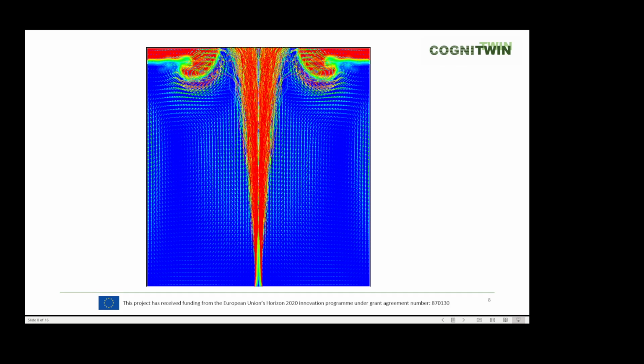On the top there is red slag, which is being pushed to the side by the upcoming steel flow. And the arrows that we see indicate the flows in the steel. So we simulated a number of scenarios here with different gas flow rates and also different vacuum pressures above the melt. The vacuum pressure above the melt is important because in the case of low pressure, the gas bubbles expand dramatically in the upper part of the ladle, creating much stronger flows in the liquid.